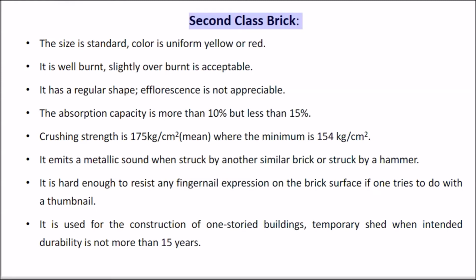Second-class brick. The size is standard, color is uniform yellow or red. It is well burnt, slightly overburnt is acceptable. It has a regular shape, efflorescence is not appreciable.